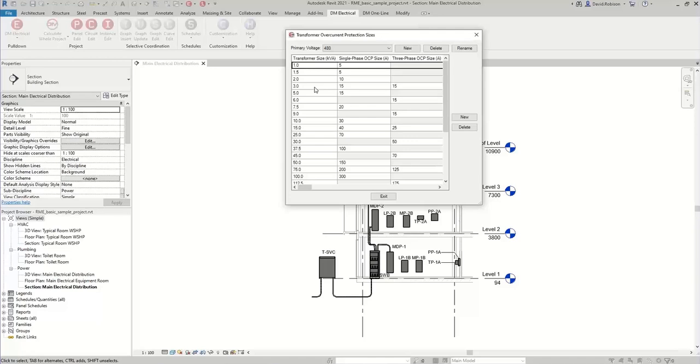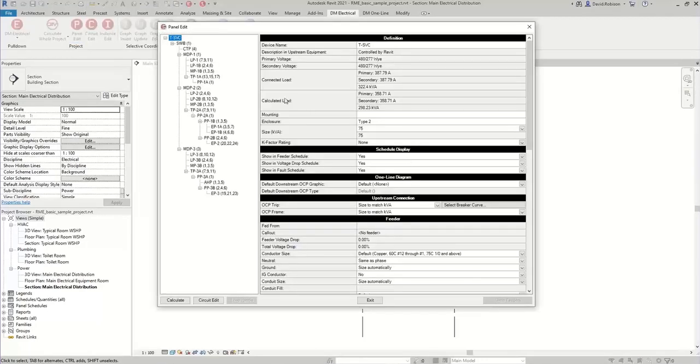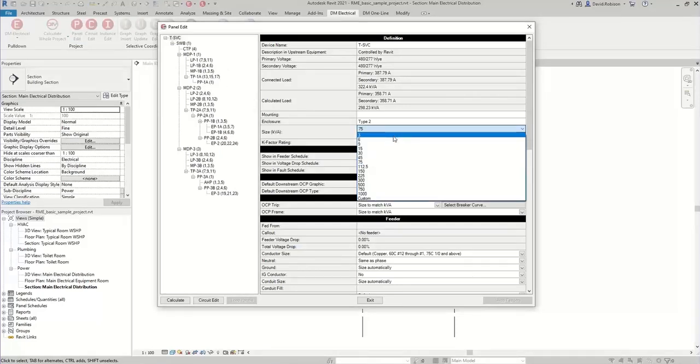We were trying to include a list of defaults, but different people go down to different smaller sizes and larger sizes. So we decided to implement this to give you better control over what size transformers you typically use in your projects. If you're never using anything small and you don't want to see those in the list, you could get rid of these here, and then we're not going to see those smaller size transformers anymore. You can still set it with the custom size, but it's not going to show up in the pull down. And that pull down is over in the panel edit command. If I run that and select this transformer for the sizes, you'll see that we've got the 3 and the 6, 9, but those smaller sizes we removed are not there.